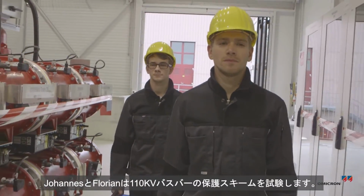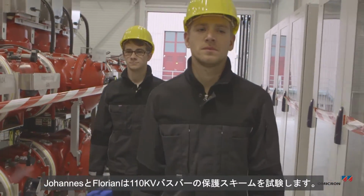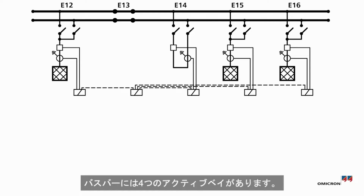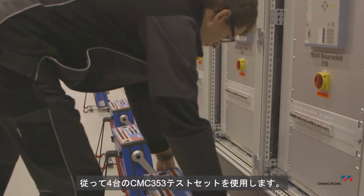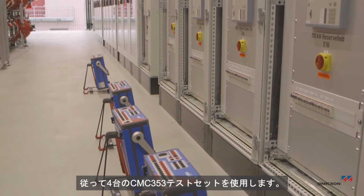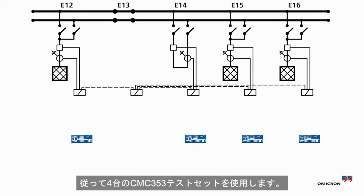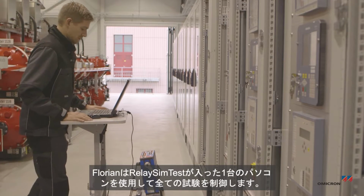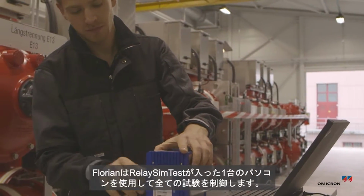Johannes and Florian are going to test the protection scheme of a 110 kV bus bar. The bus bar has 4 active bays. Therefore, they use 4 CMC 353 test sets. Florian uses his laptop to control the entire test with RelaySimTest.